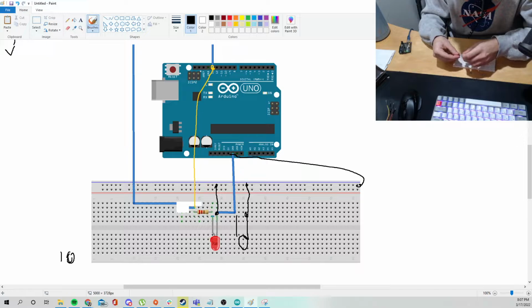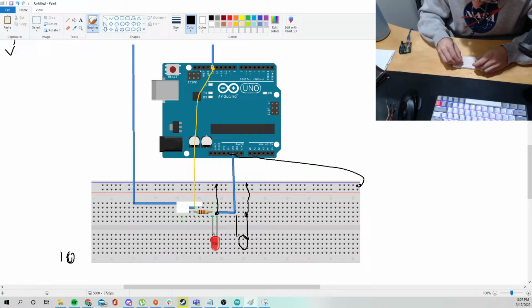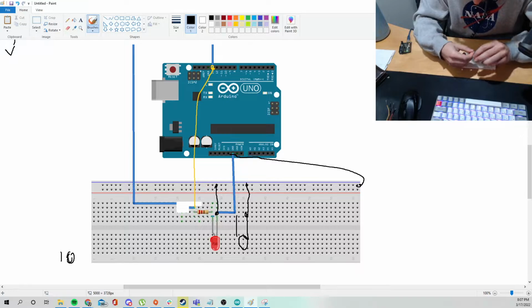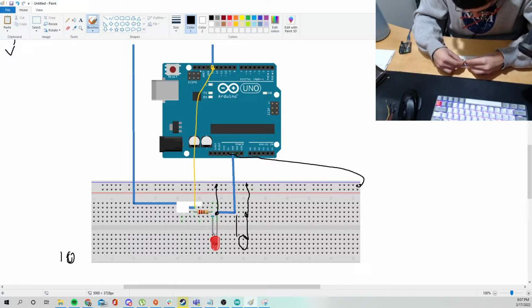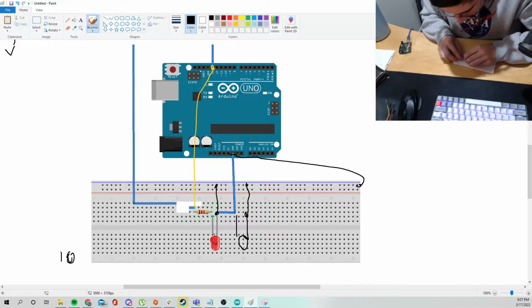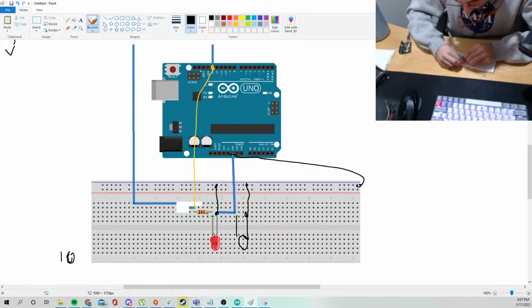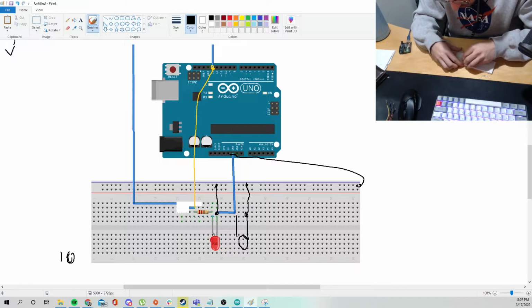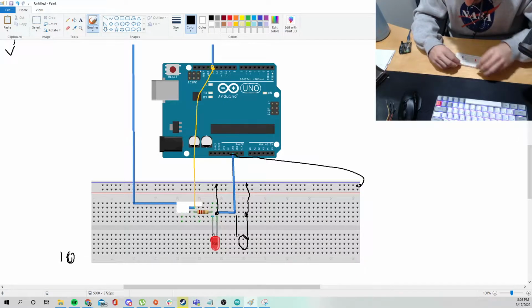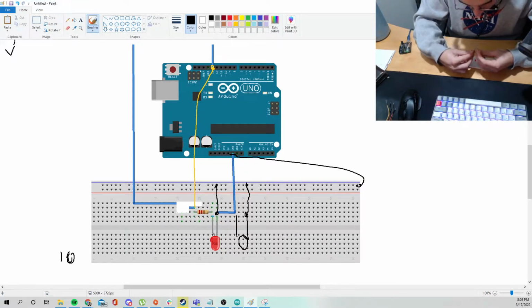I'm gonna open some space for this one and do it over here, just because I want to ensure that I have enough space, because the resistors are kind of hard to put in actually. So these again are 220 ohm resistors. This one's gonna go here, this one's gonna go here. Make sure they're actually connected to the breadboard, because otherwise you're gonna have trouble turning them on.